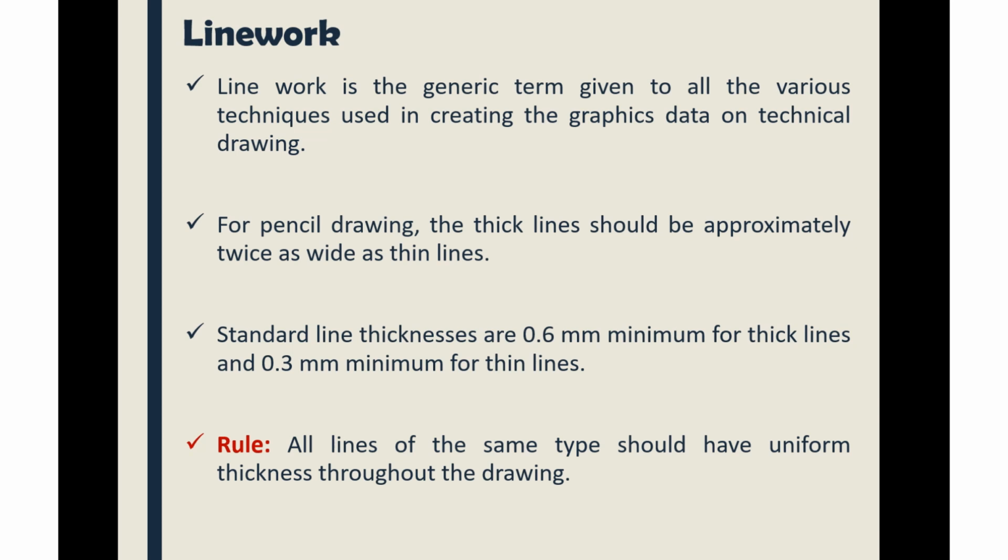The standard thickness for a thick line is 0.6 mm. That is the standard thickness. The minimum for it is 0.6. And then the minimum for a thin line is 0.3 mm. Some of you by now must have probably bought the clutch pencil. That's the refillable pencil. If you observe, they put the thickness on the body of that pencil, and the thickness depicts the thickness of the lead used in it.